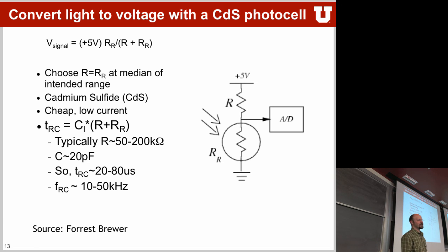Because many sensors use voltage dividers to actually give you an output signal. So a voltage divider is nothing else than something that divides a signal that you have into half or a third or something like that. The very simplest circuit is something like this, where you have two resistors, right? You have a voltage up here, two resistors, and then you can find the voltage over here by 5 volts times the resistor R2, so the resistor down here, divided by the total resistance.